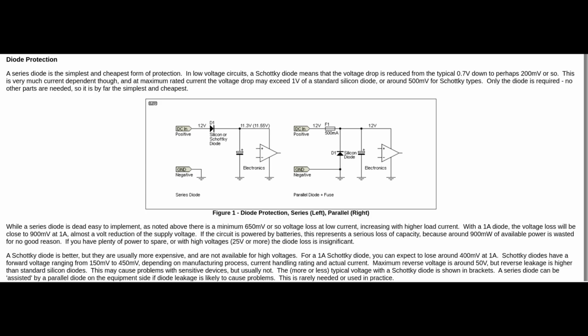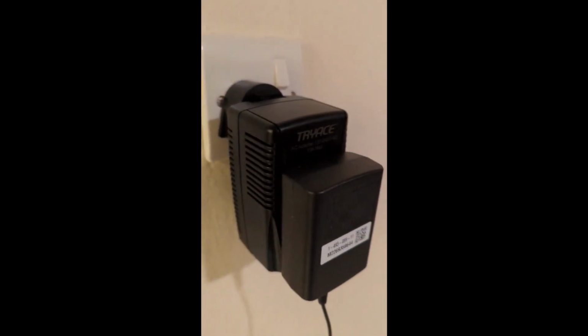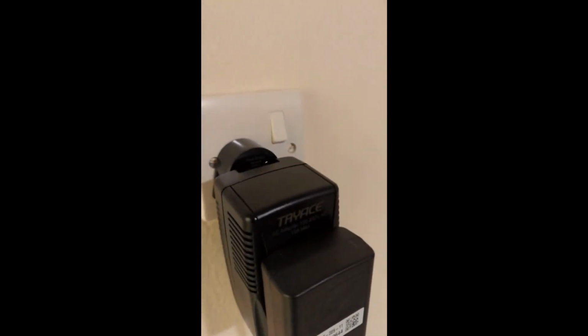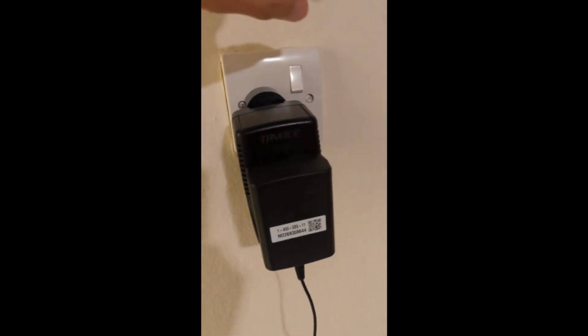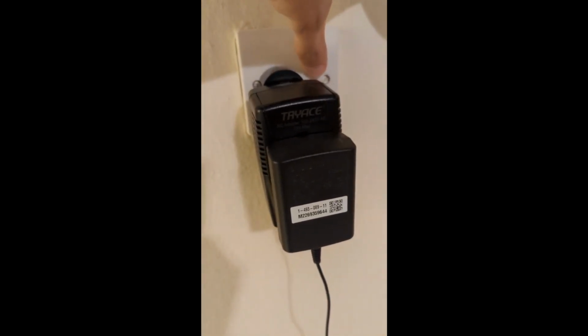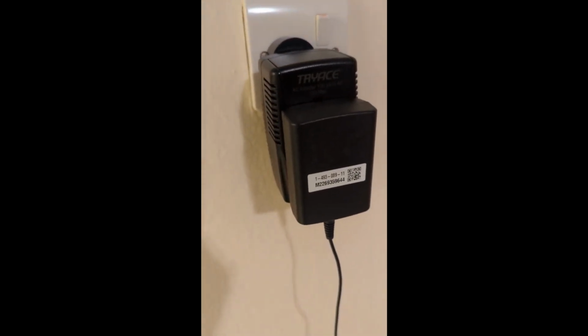However, when you connect the diode in series, it will create some heat that then again needs to be transferred to the radiator. So what Sony did, they connected it through the fuse. In my opinion, it's not really good. However, they know better. So I connected it directly, so there is no protection at all. If you do something wrong, then it's finished. So let's check how it works.